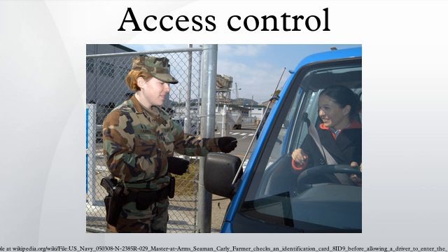7. IP readers. Readers are connected to a host PC via Ethernet LAN or WAN. Advantages: most IP readers are PoE-capable. This feature makes it very easy to provide battery-backed power to the entire system, including the locks and various types of detectors. IP readers eliminate the need for controller enclosures. There is no wasted capacity when using IP readers. IP reader systems scale easily. There is no need to install new main or sub-controllers. Failure of one IP reader does not affect any other readers in the system.